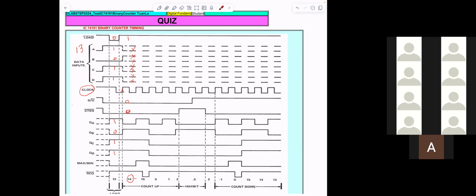Okay. You know, in your clock, you have a second, minute, and hour. So the first counter will be counting the seconds. If it goes up to 60 seconds, it sends out the logic. So the next circuitry looks at that, and now it counts 1 minute.